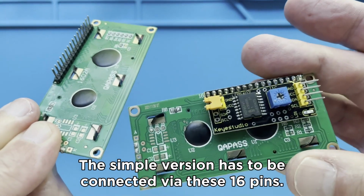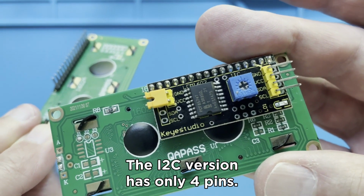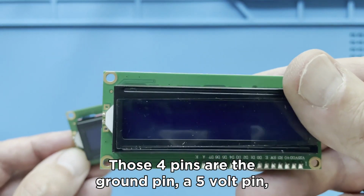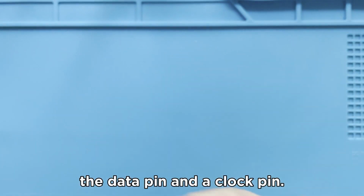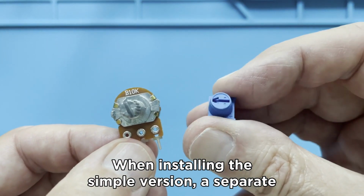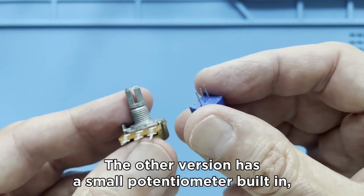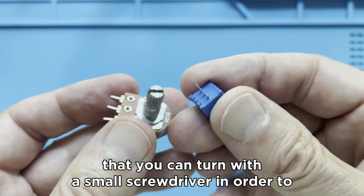The simple version has to be connected via these 16 pins. The I2C version has only 4 pins. Those 4 pins are the ground pin, a 5-volt pin, the data pin, and a clock pin. When installing the simple version, a separate potentiometer to control the brightness of the display is needed. The other version has a small potentiometer built in that you can turn with a small screwdriver in order to